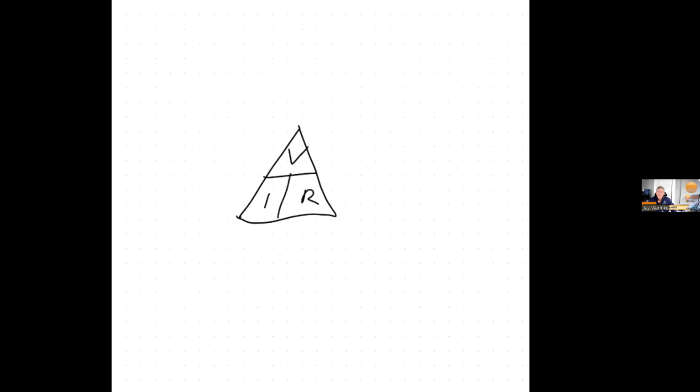All right. So if we're solving for volts, it's going to be amps times resistance. If I'm solving for resistance, it's going to be V over I, or volts divided by amps. If I'm solving for amps, it's going to be volts divided by resistance. So you can just look at it and see what is the equation that we're going to be solving for without having to figure out the algebra. The same thing could be done for watts equals amps times volts. It's just putting the watts in there, and it just helps you if algebra is not your strong suit.